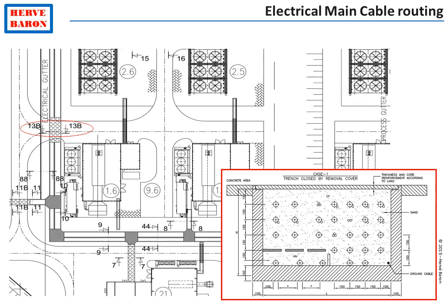Electrical cable ways are wide. Indeed, electrical cables, contrary to instrument cables, must be separated with a separation distance allowing the heat to dissipate from the power cable. Therefore, the cable trenches occupy a large footprint.